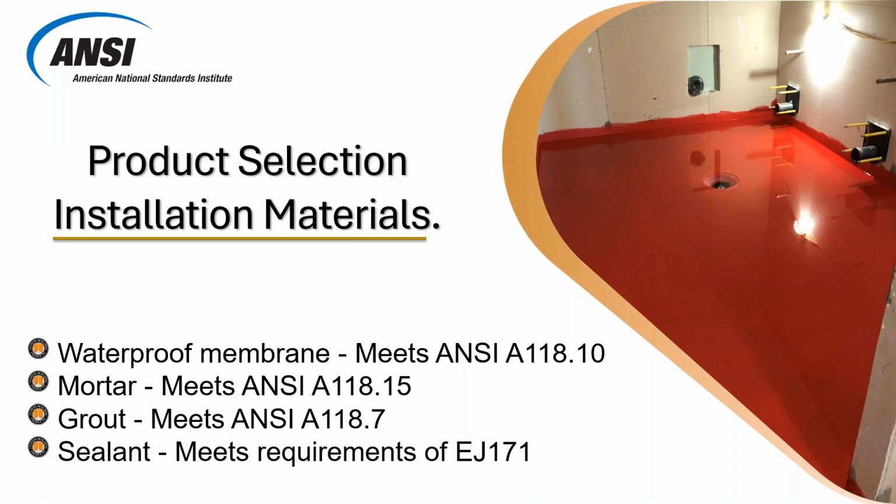When it comes to the installation materials, these are the selections that are most important. Waterproofing membranes must meet ANSI 118.10. Tile mortar must meet ANSI 118.15. And the grout must meet ANSI 118.7. Sealant must meet all the requirements of EJ 171 in the Tile Council handbook. Now, I'm going to spend some time on each one of these later and tell you why these particular standards were selected for exterior applications.